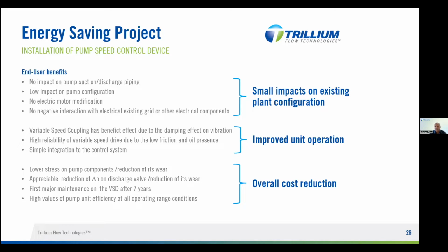In terms of operation, we will see an improvement because with the use of a variable speed coupling, we can have benefit on damping and vibration. We can have high reliability in using the variable speed coupling, and there is a really simple integration to the existing control system.